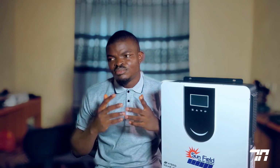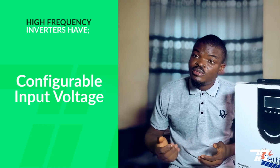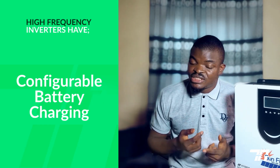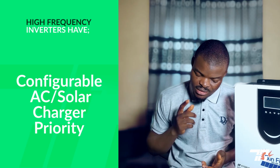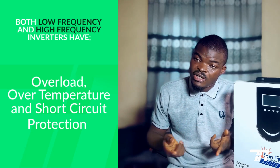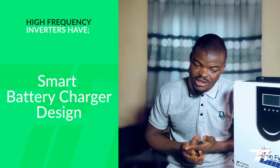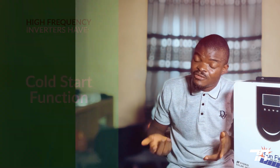The first one is pure sine wave. The inverters are pure sine wave. Configurable input voltage, configurable battery charging current, and configurable solar charge priority. Compatible with mains and generator. Overload, over temperature, short circuit protection, smart battery charger design, cold start function.